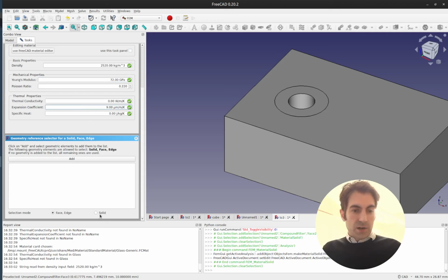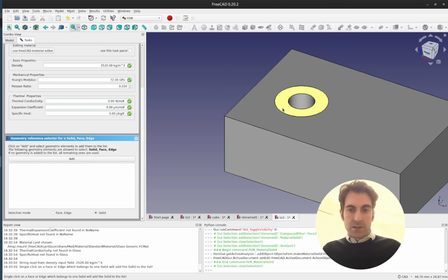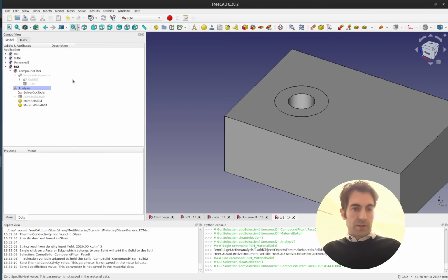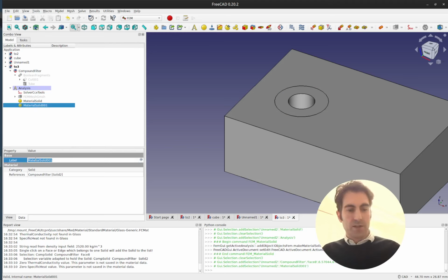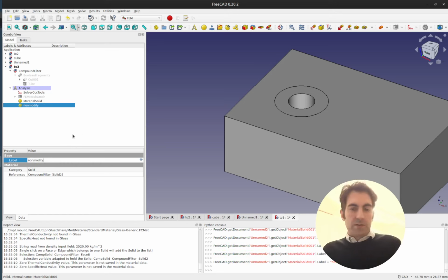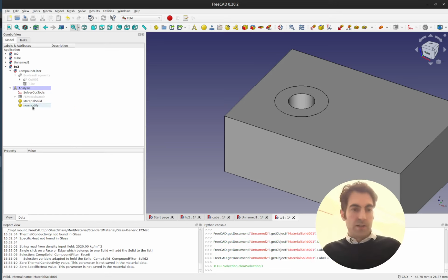So that means now I'm choosing this material and giving it another material parameter. The only difference is the Young's modulus and the Poisson ratio, and the mass density, which we don't use because we do static analysis. So in order to have a little bit better access, I can change the name. It's optional, of course, but I can say non-modify, right? So it's a non-modifiable domain in my eyes. This is why I'm giving the name non-modify.